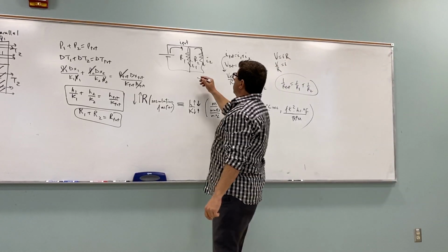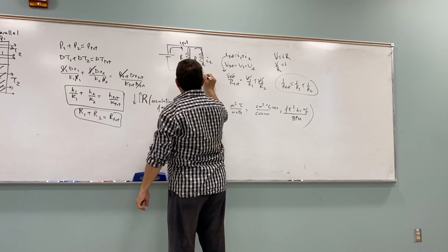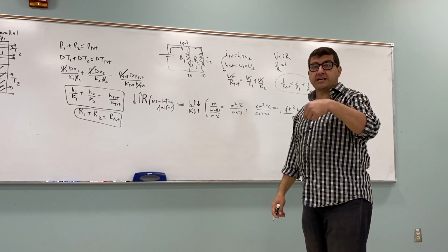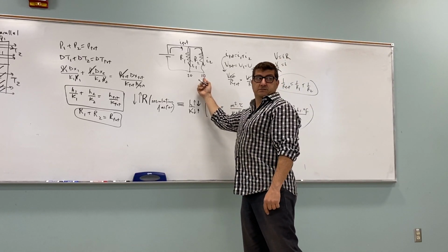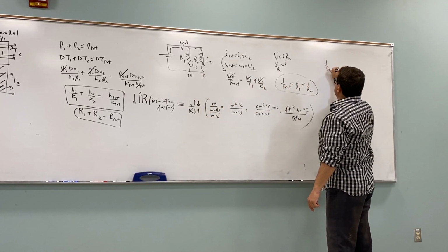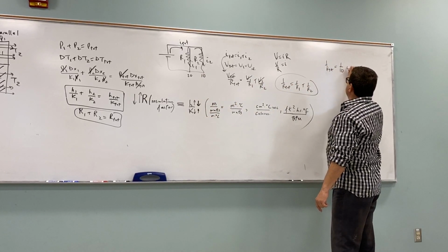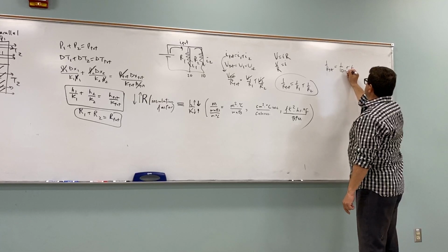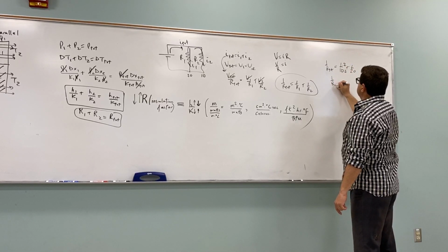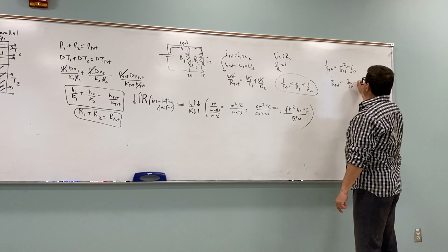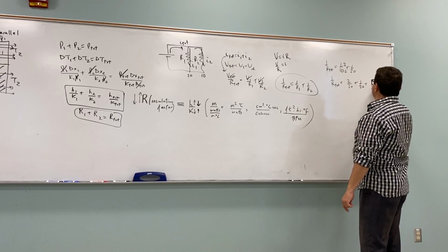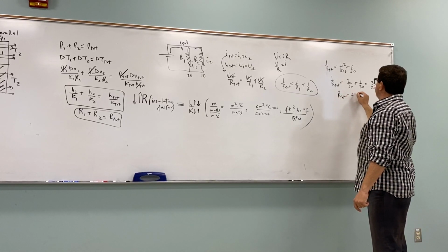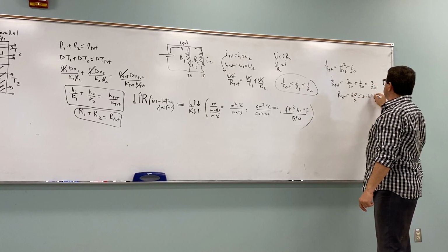So if you take a 20 ohm resistor and a 10 ohm resistor, right, and you put them in parallel, the net resistance should be less than even the 10, right? So it's going to be 1 over R total, 1 over the 10 plus 1 over the 20, right? So then you can get a common denominator, 2 over 20 plus 1 over 20 is 3 over 20, and then reciprocate it again. R total is 20 over 3, 6.67 ohms.